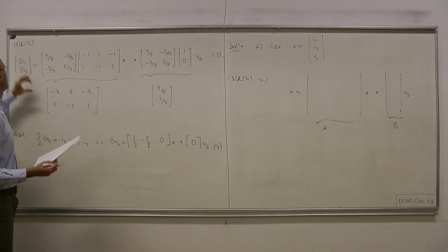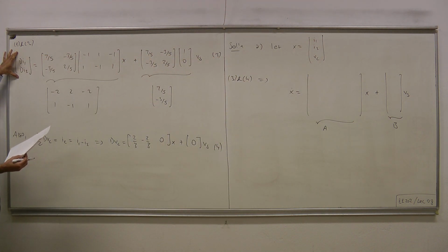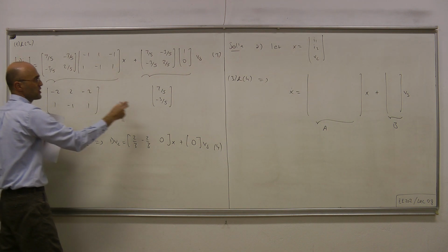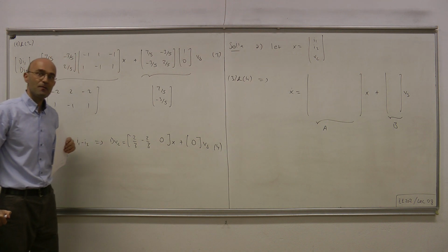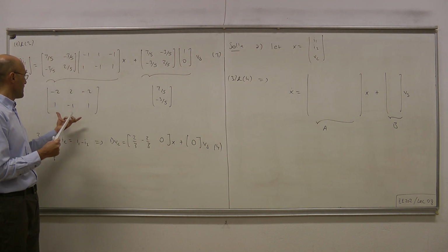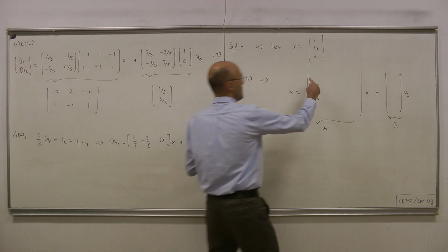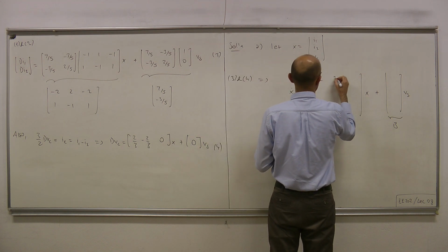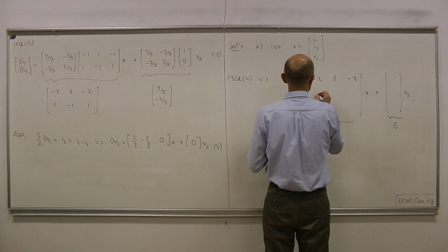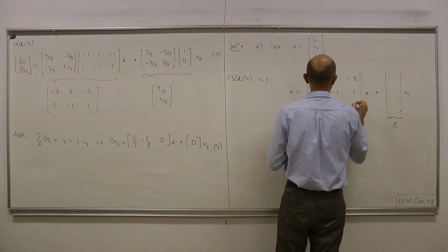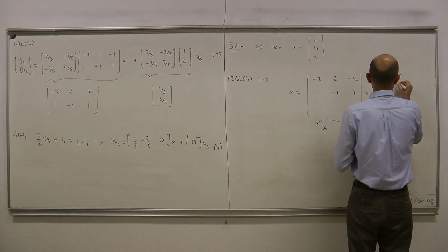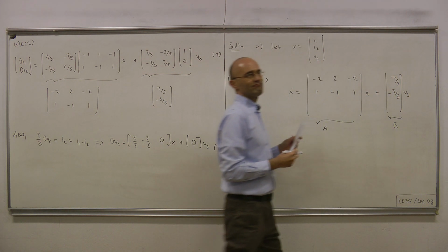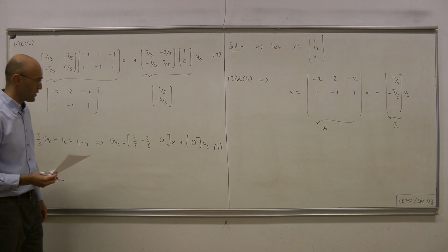I1 dot, I2 dot is here in block form. And it's in the form something times x plus something times Vs. Therefore that something must be this block here. So what we do is we just directly copy those entries, minus 1, 1, and 7 over 5, minus 3 over 5. It's very straightforward.